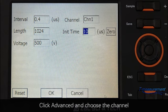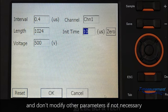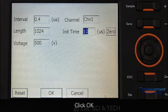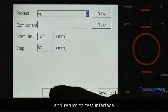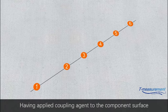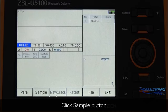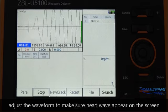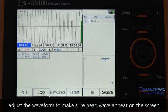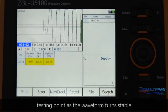Click Advanced and choose the channel the planar transducer connects to. It is suggested to take 0 setting before test, and don't modify other parameters if not necessary. Click OK and return to test interface. First of all, take a non-crack cross data test. Having applied coupling agent to the component surface, press planar transducers on the first 2 testing points. Click Sample button, adjust the waveform to make sure head wave appears on the screen. Press Save button to store the data of the first testing point as the waveform turns stable.